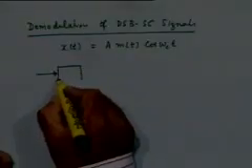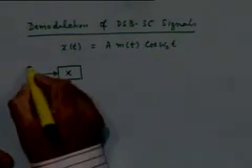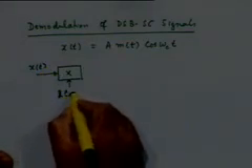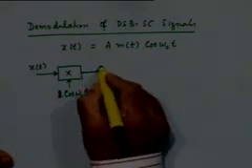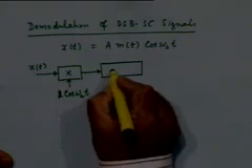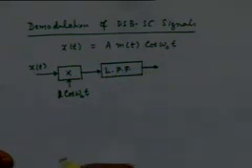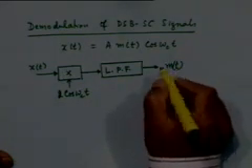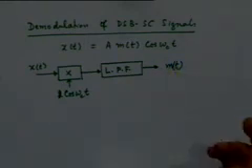And therefore, the demodulator will have the same multiplier that we had at the transmitter, which will multiply the received signal with the carrier 2 cosine omega ct and followed by a low pass filter. And hopefully this should be a replica of the message signal m of t, maybe with a scaling constant, etc.